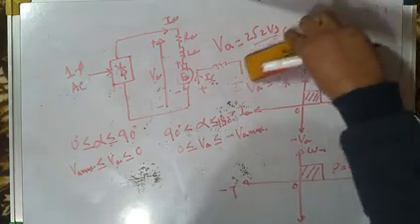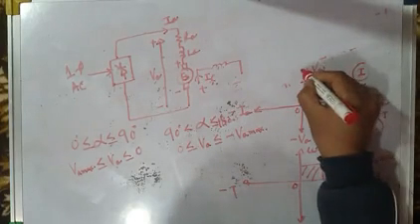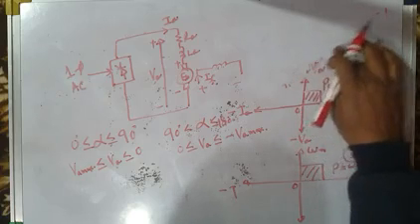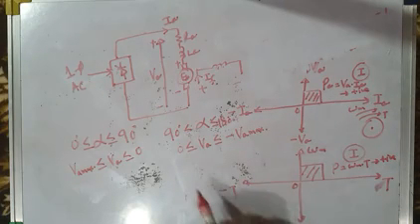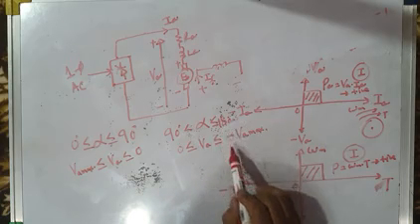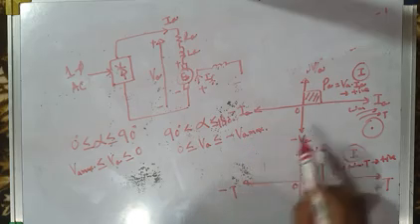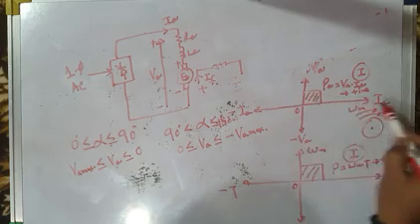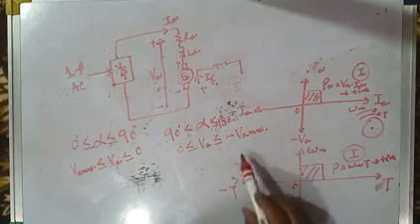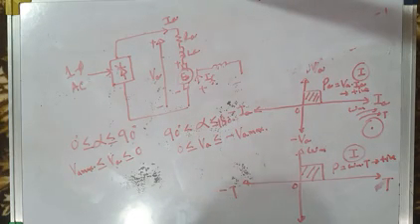So therefore, for alpha greater than 90 degrees, up to 180 degrees, this mathematical equation tells us that the average output voltage becomes negative, till at alpha equal to 180 degrees, it becomes maximum negative, VA max. And in this four quadrant characteristic, VA versus IA characteristic, what is the negative voltage? Current will still remain positive, but average output voltage will become negative.